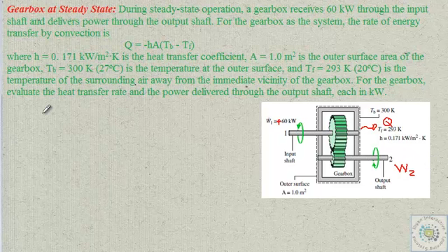Now, you can always remember that we'll have this formula. This is a closed system. No mass enters and no mass leaves. So you could use this principle: delta U is equal to Q plus W. But this is not on a time basis. This is essentially the total change in internal energy, which will just equal the Q heat added to it and the work done to your system.